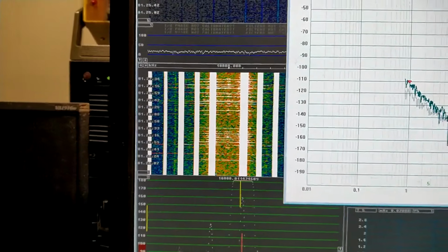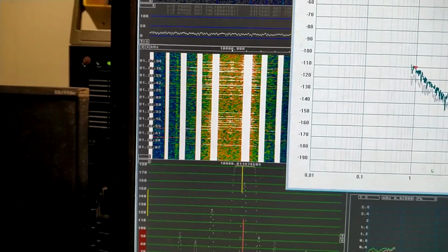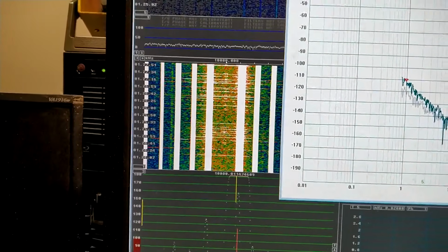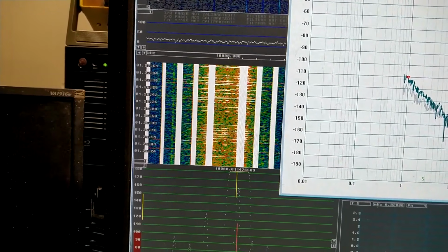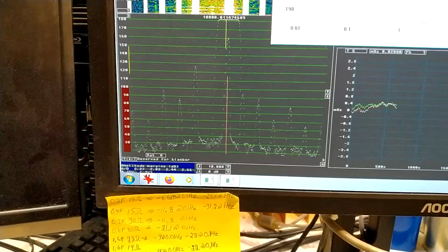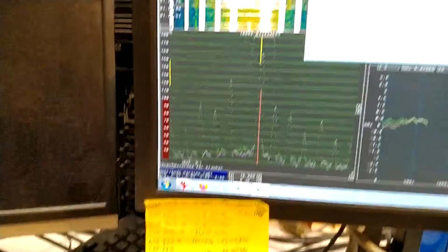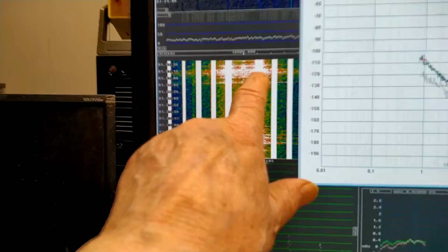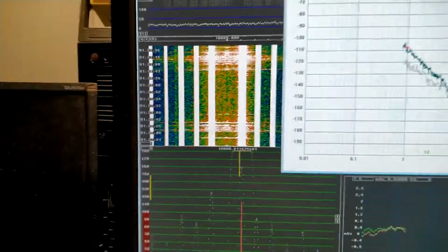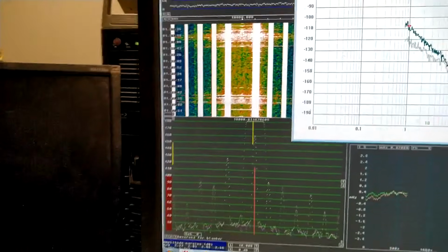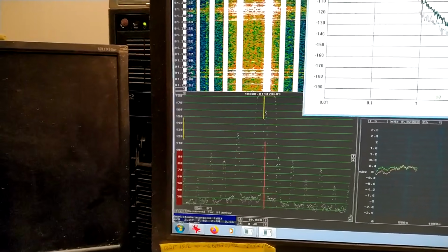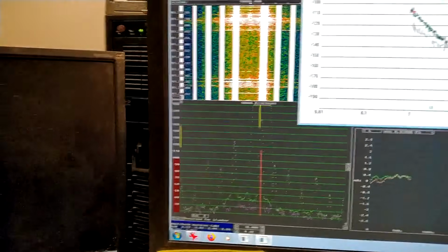These amplitude problems in channel 1 do not affect the frequency determination, so I will not try to fix it right now. It seems that the interference is equally strong on the mirror image as on the main signal, and that indicates that the problem is in the signal path and not in the oscillator path.